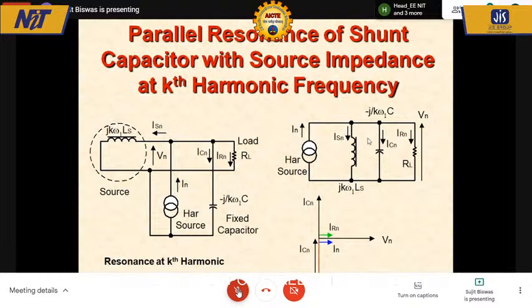It can trip all the breakers. It can trip your capacitors. It can damage your capacitors because the current becomes very large. Something more important is your source current is also going to be very large for that particular harmonic. So when you look at the source current back here, when you monitor near your metering system, you'll find that your system is having a large amount of harmonic current compared to the harmonic current that you have generated. You will not be able to understand what is happening. Your harmonic current source is a small magnitude here, but the current that is coming in from the source into your premises can be very, very large, as shown here, ISN.